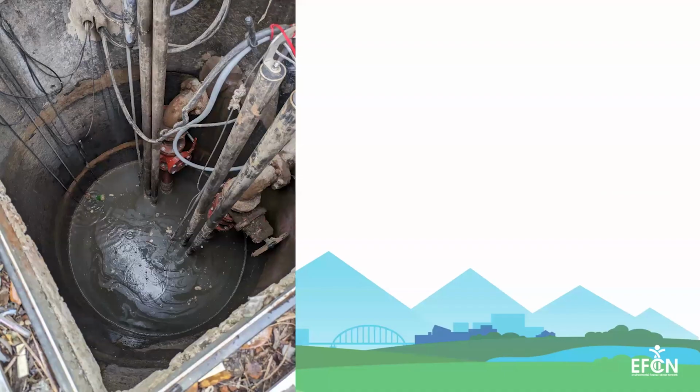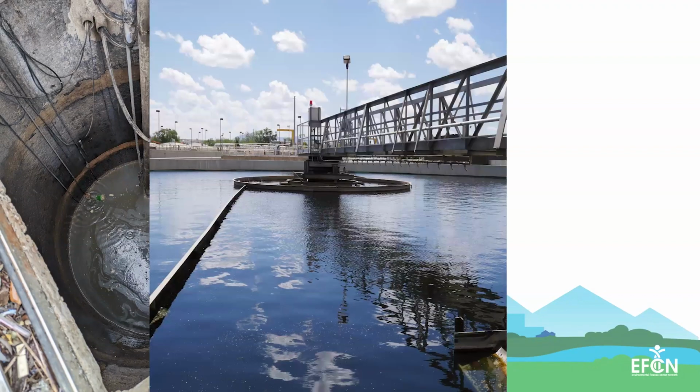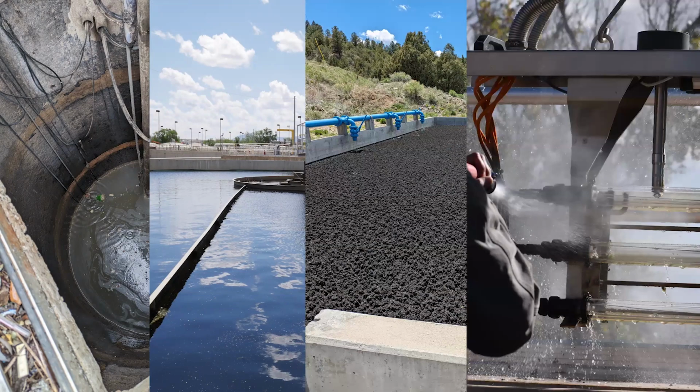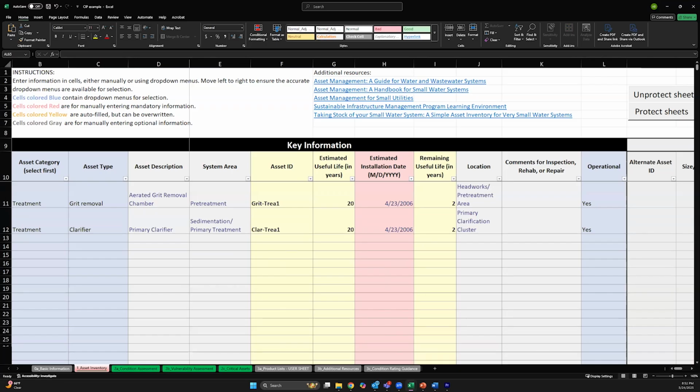For this scenario, we will imagine a small wastewater system that manages their collection system and wastewater treatment plant. The wastewater treatment plant has a screening facility with an aerated grit chamber, primary and secondary clarification, activated sludge, drying beds, and a UV disinfection facility. For this exercise, we have identified 3 assets that we want to evaluate and plug them into our SCAP tool. We already filled the information for the grit removal system, the primary clarifiers, and now we'll complete the critical information for the activated sludge mixers.